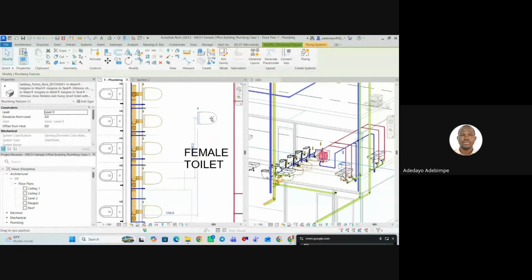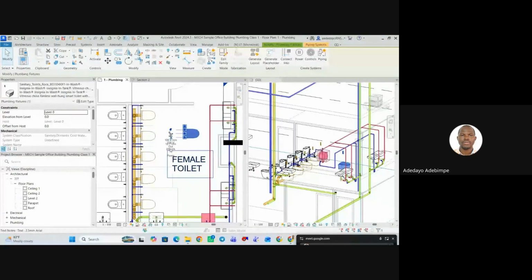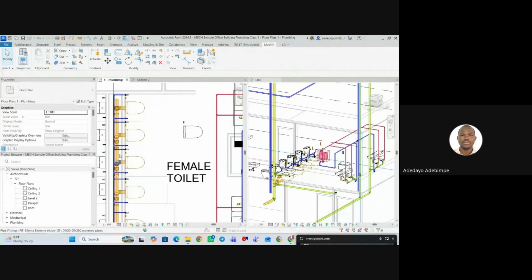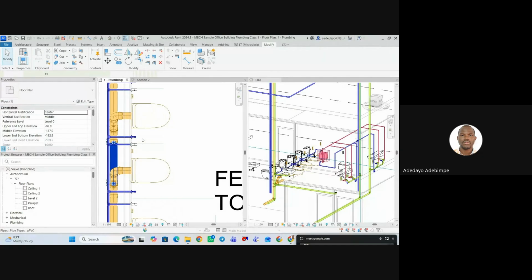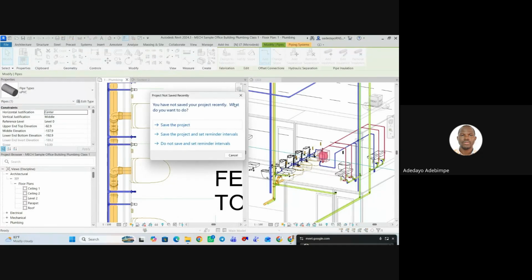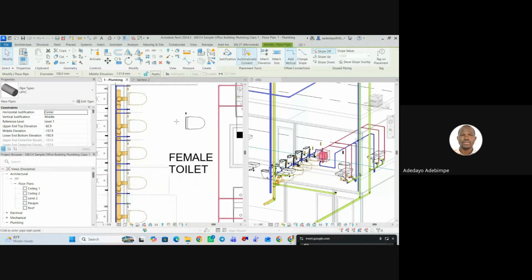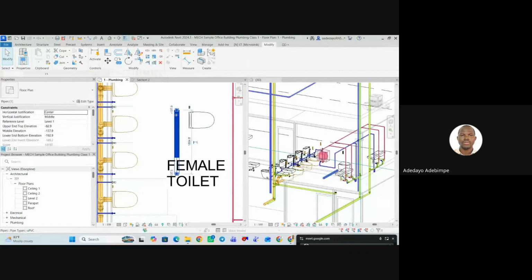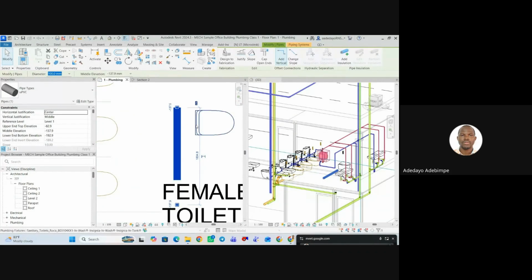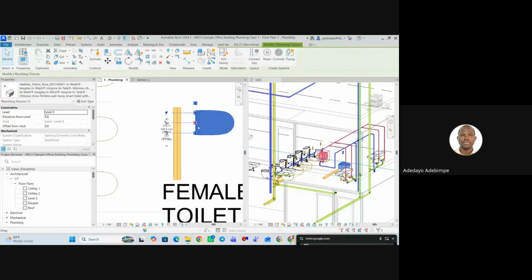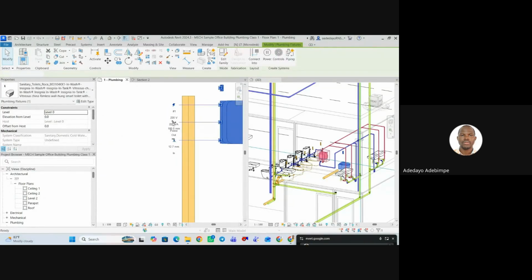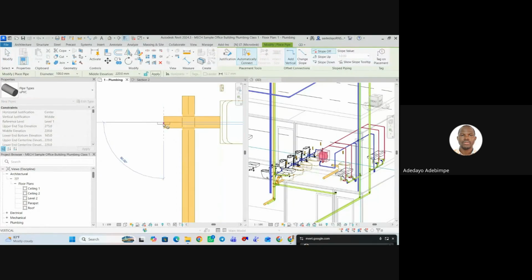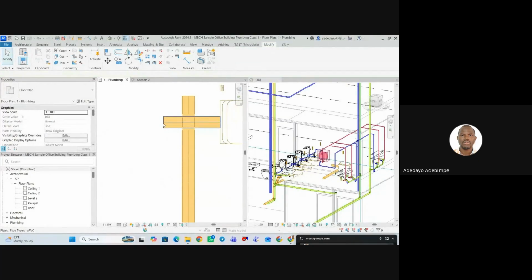Now let me quickly duplicate the sanitary ware. Let me create a similar for this pipe. Create similar. I would like you to follow closely. Now, we are trying to connect this sanitary into this pipe, but I don't want it to be a T. I'll click on my sanitary ware, draw out my pipe. You see that I have overextended my pipe, and there's a reason why.